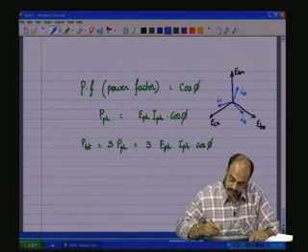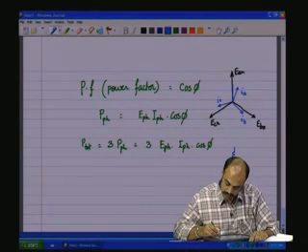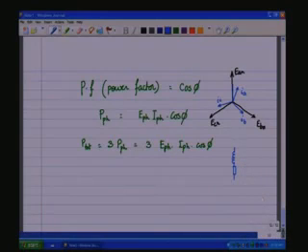How does this come about? You will see that if you have a circuit something like that, as shown here, this is A, B and C, and this is inductive in nature, an RL circuit: R, L, R, L, R and L, same R's and L's, a balanced load. So, you will see the currents lagging the voltage in every phase.